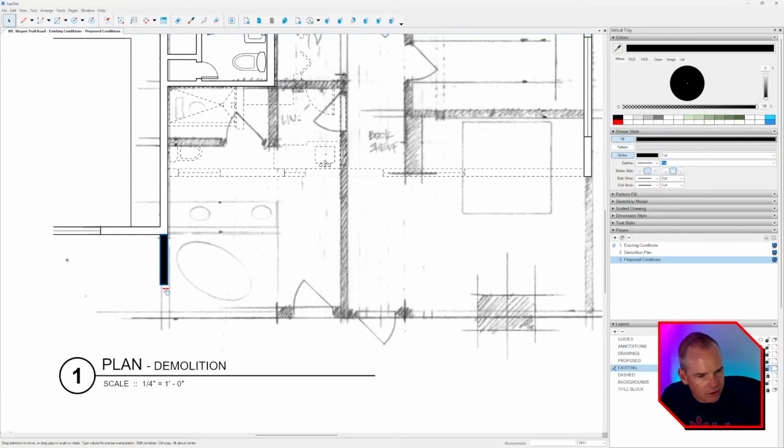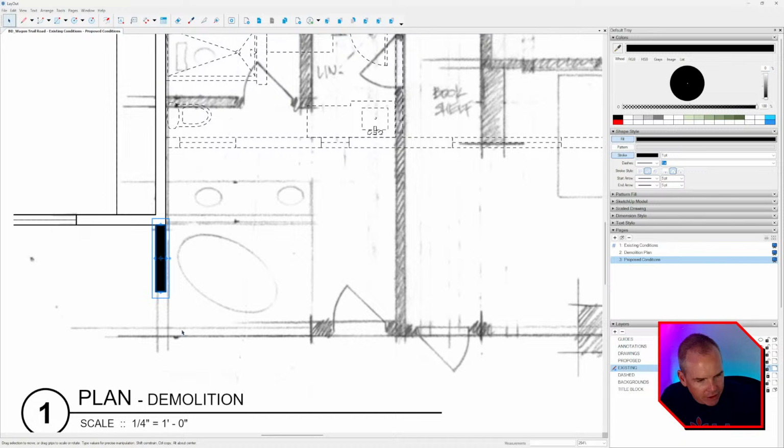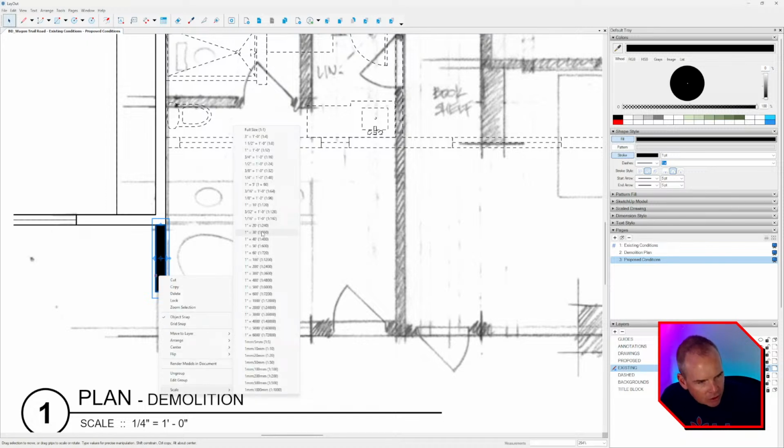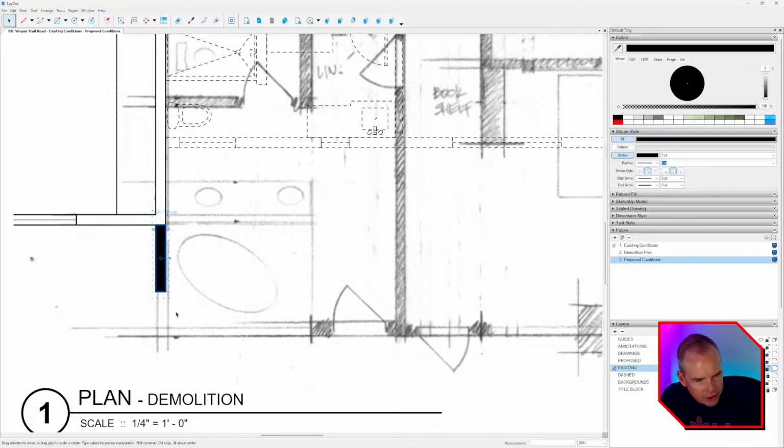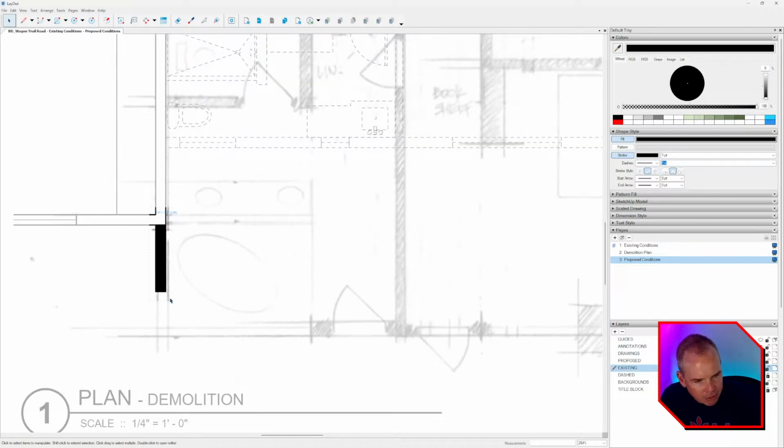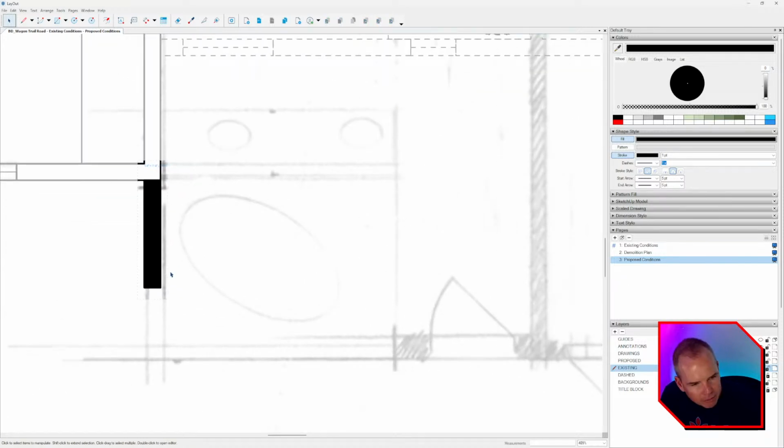All right, so this is where I could make this into a group. And then I could assign a scale to the group of like 1/4 inch. And then I could double click in, and I'd use my line tool to measure from here to here. And I'm looking in the bottom right corner of my screen. It's 65 3/4 inch. So that would be a good question.